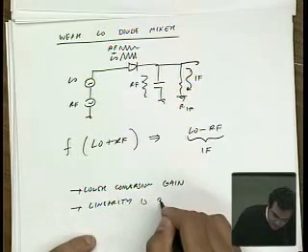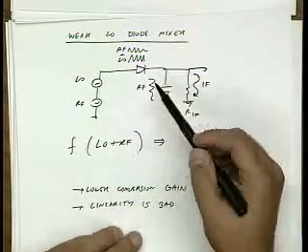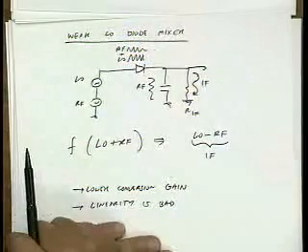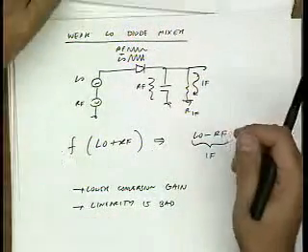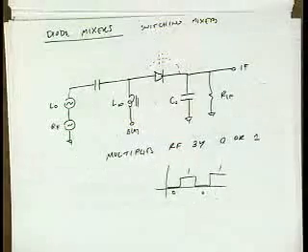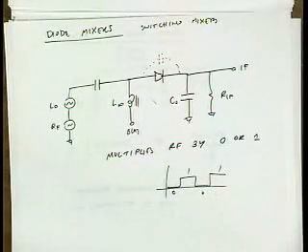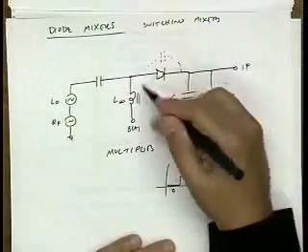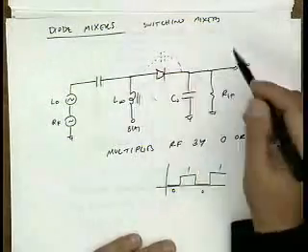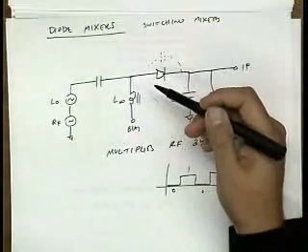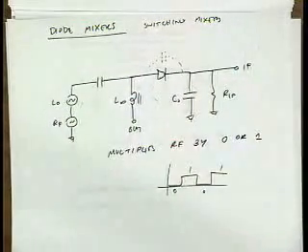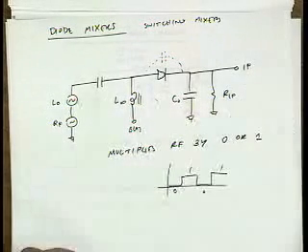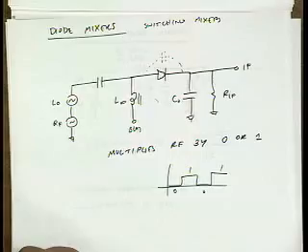Because we're relying on the nonlinear characteristic of this diode to generate the mixing, it's going to generate lots of mixing products, right? Why is this circuit not nonlinear? Because the diode is either on or it's off, right? So we're not relying on the diode characteristics. We're relying on the time-varying nature of the circuit. So we're always trying to build mixers that take advantage of time-varying behavior to mix rather than nonlinearity. Okay?